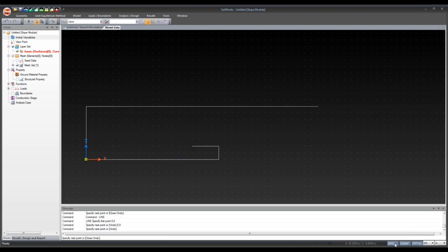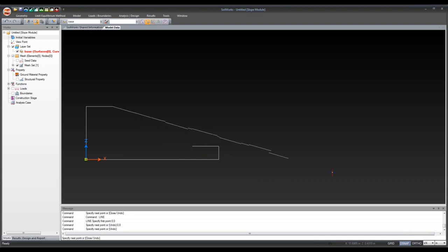Now I can turn the grid option off, actually, and turn ortho off. Then I'll be able to seamlessly snap onto that base point there. As you can see, when I have ortho on, I can't directly snap on here, because ortho restricts my movement to completely straight lines from that base or reference point. So turn that off, and turn grid off too, because each of the grid points can be automatically snapped on, which makes it a little harder to choose the point I want. So just click off grid, and now I have the basis of my slope.